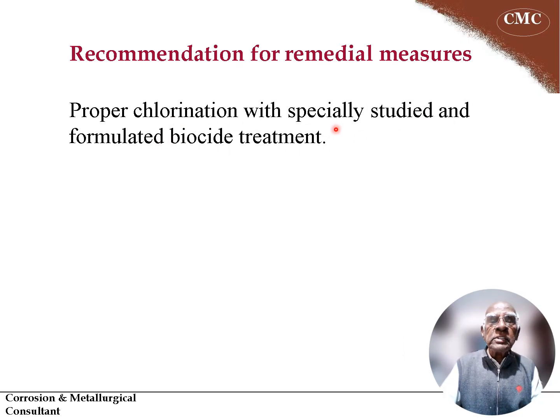Any cooling water systems require chlorination. Unfortunately, it is not being done in this case. And now, as a result of this case study, the proper biocide has been used so that it will kill the bacteria and stop this problem. Thank you very much.